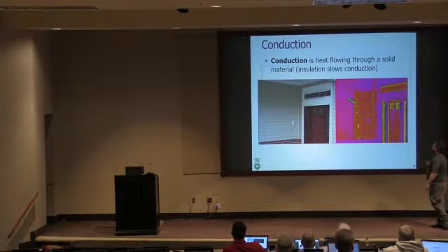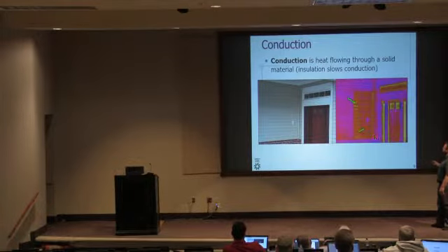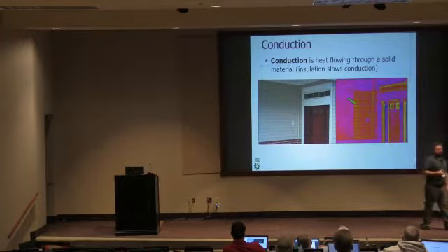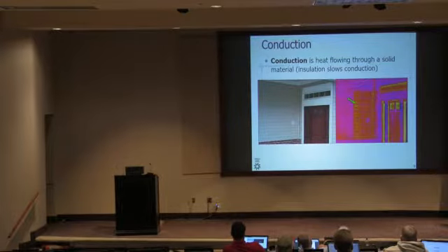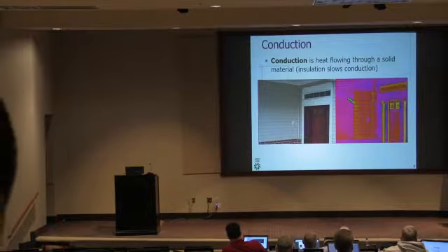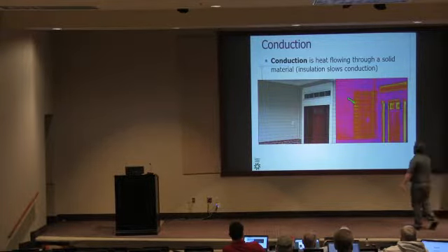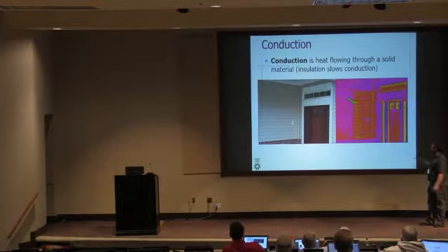So we think it's possible that, some people say, maybe there was going to be a window there and they changed it. That's possible. Maybe this guy that wired this in tore all the insulation out, trying to figure out how he was going to wire this doorbell. We also think maybe, y'all have seen a shower stall that comes out and it's just installed, they put it in the framing. You see that all the time. They set that on that exterior wall, then the insulator comes later and hangs the insulation behind it. That's also potentially what's going on here. But regardless of how it happened, you can see that's a big thermal bypass in that wall.